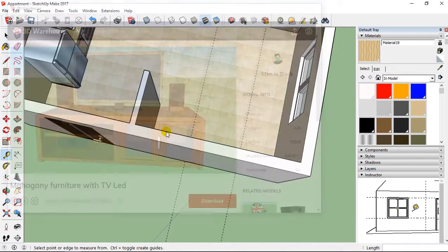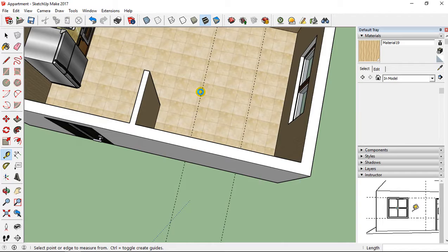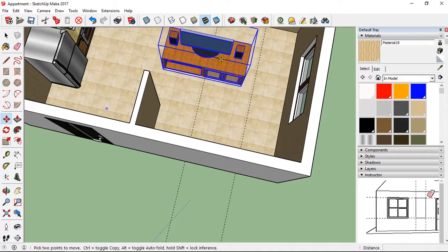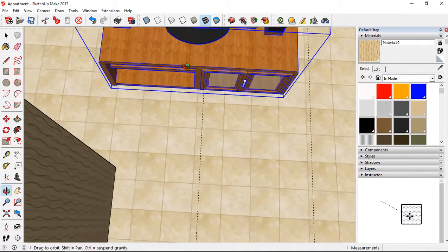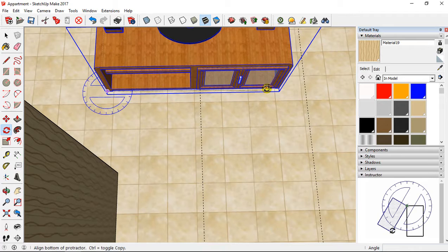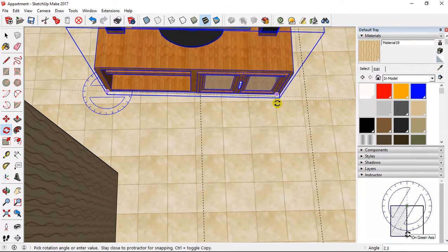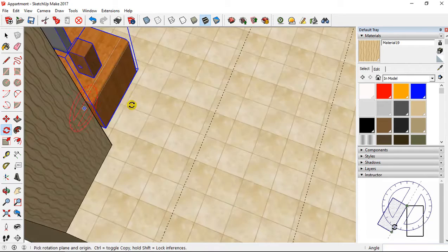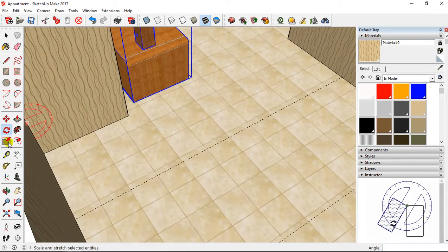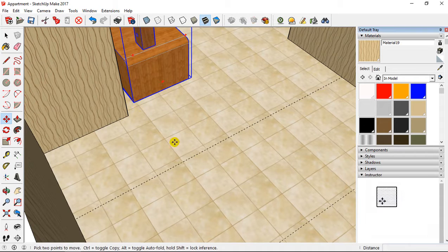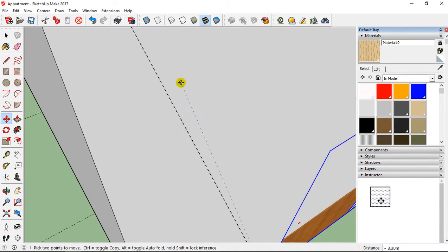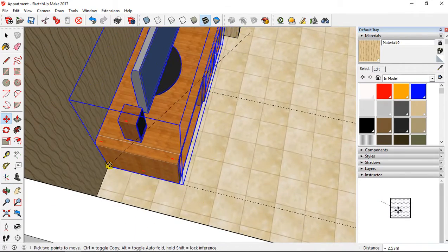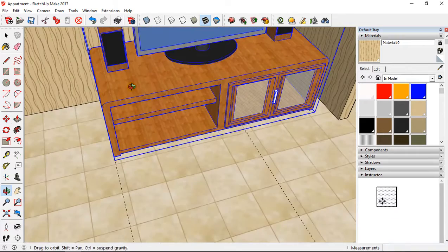And I can add this furniture directly. So I add this furniture here. I'm going to create a rotation. So rotation tool, blue X, you take an endpoint, the other endpoint, and you can turn 180 degrees, like this. Then I'm going to take the move tool to take the endpoint in component, and I'm going to place that here, like this, to the intersection.